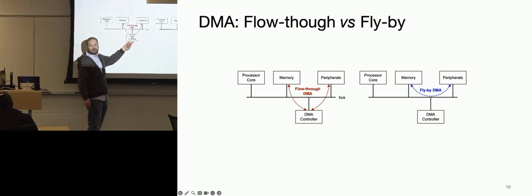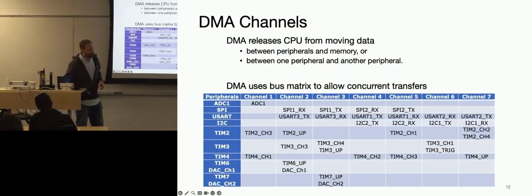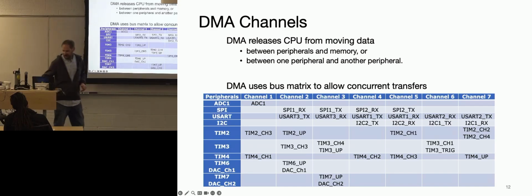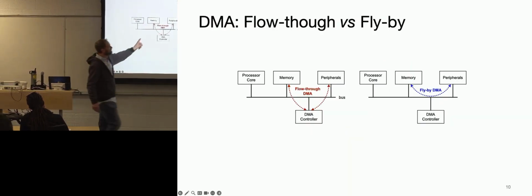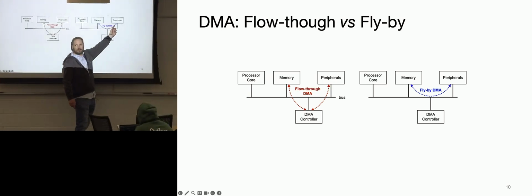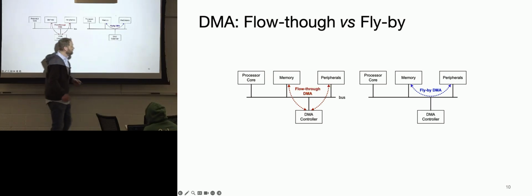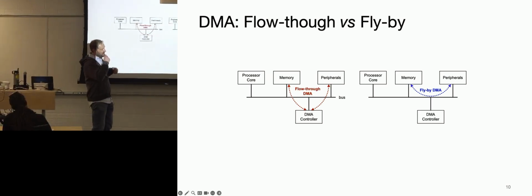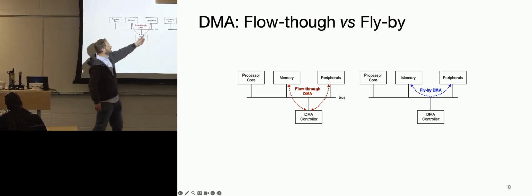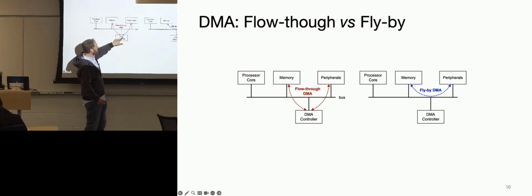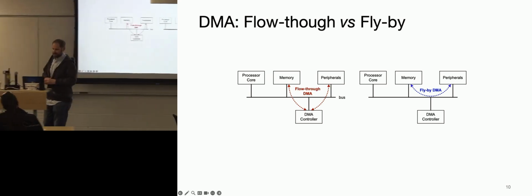And the problem here with this one is it takes 2 memory transfers. So how does that relate to the diagram? I think it's just telling you these are the things that can be connected per channel. And the real constraint between which one you choose is the speed of your peripheral, right? If it's a very slow peripheral, you don't want to hog that channel the whole time. But if it's an incremental thing where you would want to release channel 1, let's say, then you just use channel 1 for a moment, have your DMA hold it, and whenever it's available, you can have a blocking thing at channel 1, then it'll talk to memory. Okay.